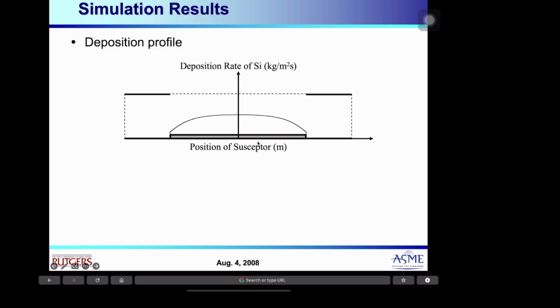If you try to grow silicon at the bottom, you want it to be flat, right? You don't want it to be dome shaped, because in semiconductors you want everything to be grown at an even speed. The tail of this silicon wafer cannot be used because it collapses.